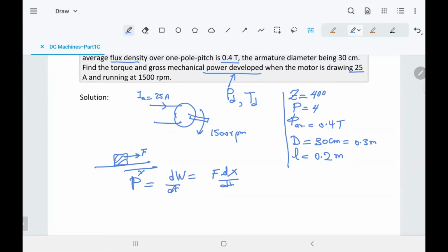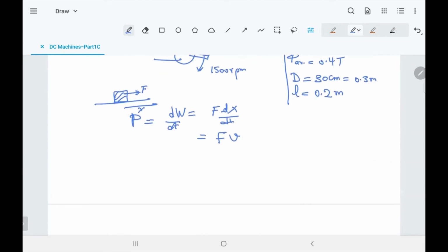So the power when something is moving in a straight line is equal to force times velocity. All right. Now let's go for something rotating. It will be very similar. Power will be equal to force, which will be torque, times velocity, which will be omega. I can prove it in the same way. So power is equal to torque times omega, and power in translational motion is equal to force times velocity.